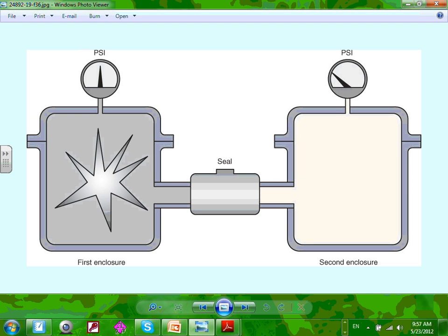That's why they seal between equipment. They have arcing and sparking devices. Any comments, guys, about this? So every equipment that has a circuit breaker, a switch, a magnetic starter, a controller, explosion proof, you have to seal between the equipment and any other equipment. Always.